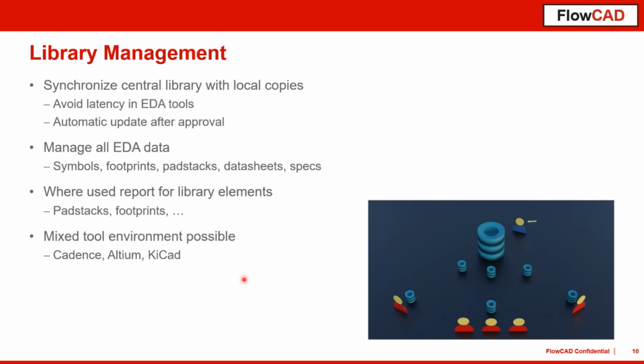I mean, if you know the day-to-day work, and you always have a latency inside of your tool when you place a schematic symbol or something, then it's really cumbersome to work. Therefore, it is really a good thing to have these local copies of the library, which are completely synchronized with the central one.